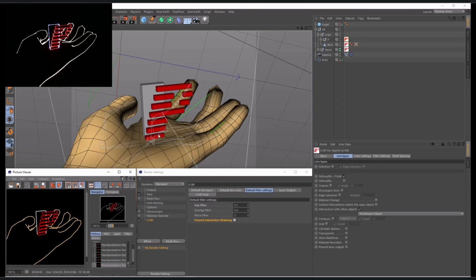And in this case, the reduction of such kind of elements is of course recognizable. So it's always somehow some kind of compromise. Nevertheless, the overall number of output points when you render this is reduced to 1290 points only. And I would consider this as already near to an acceptable limit for fast scanning systems. To show you some additional ideas of optimization, I will undo this step for now and continue with other possibilities.